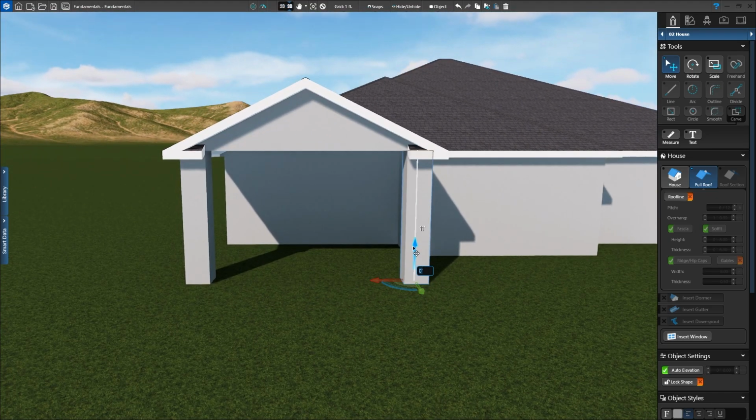One of them is selected, so we've got the gizmo on it. If you want to deselect a shape and see what it looks like without the gizmo, without the highlighting, you can go to the top of your screen in the middle of the application bar, look for the circle with the line through it. When you left click on that, you'll deselect any and all shapes that are currently selected. It's a fast way to clear everything from being selected. So now our columns are complete.